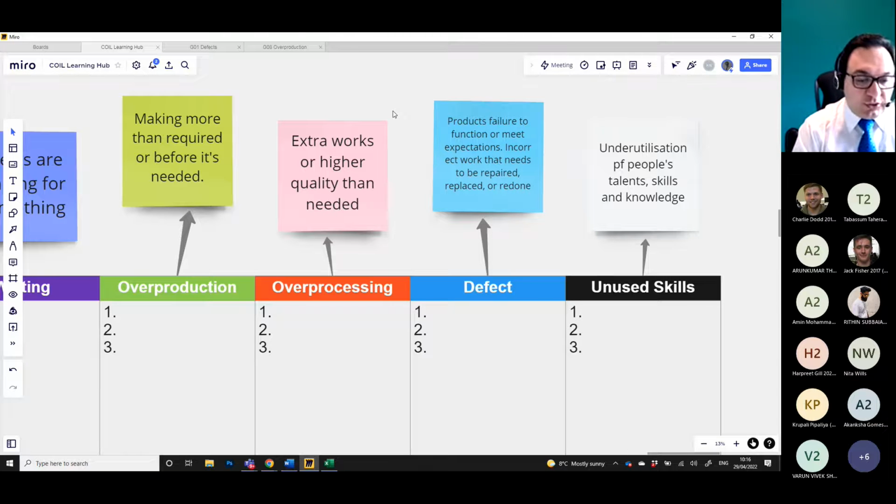For example, you have 2D drawings, then you build a BIM model based on the 2D drawings. It is a kind of waste. Interesting, isn't it? In most cases we think that BIM is very good. Yes, it is good, but you must start from the beginning. So you should create a model in BIM. In many cases, I noticed that people create 2D drawings in CAD, and then from the 2D drawings, we have some people convert them to a BIM model. Again, it is a waste of time. It is extra work that is not required. So double handling, double entry of data, is a kind of waste.